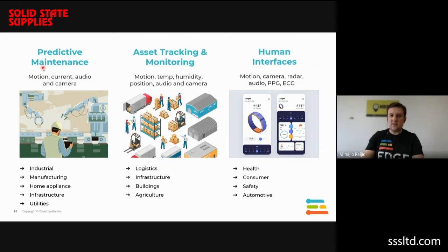So the first one is predictive maintenance. That is more than obvious. That's a typical use case where you can go into industrial applications. You look at current pattern analysis. One of the topics we are working on heavily at the moment is motor current signature analysis for electrical motors, by which you can classify very easily and fast certain imbalances, bearing faults, misalignment, and things like that.